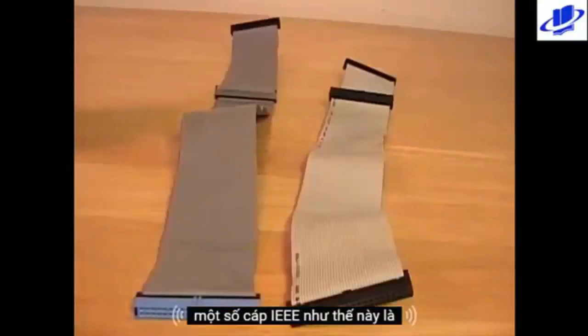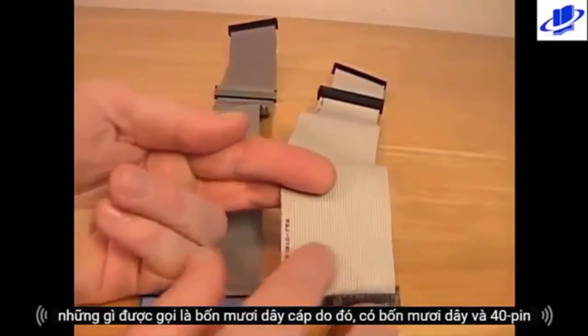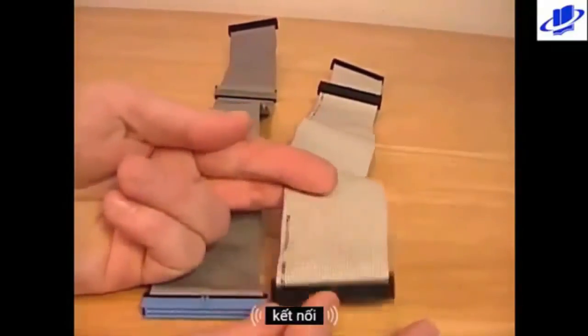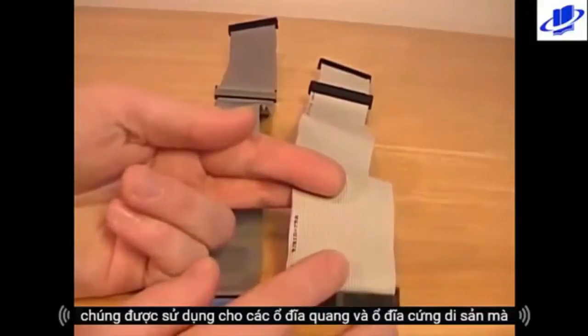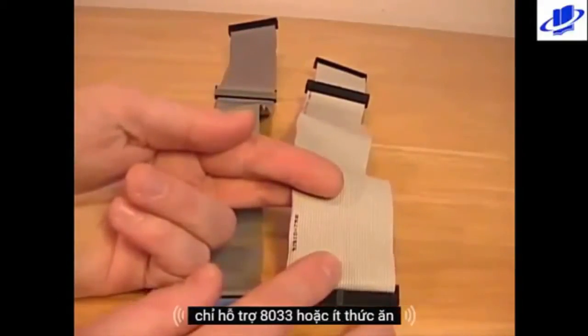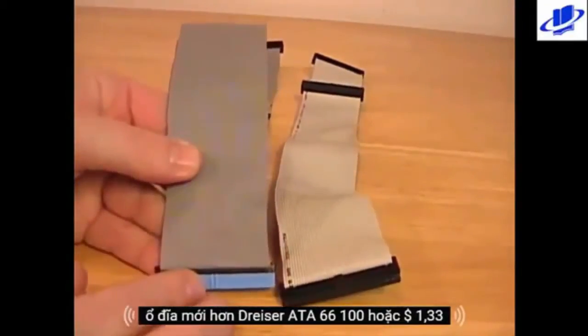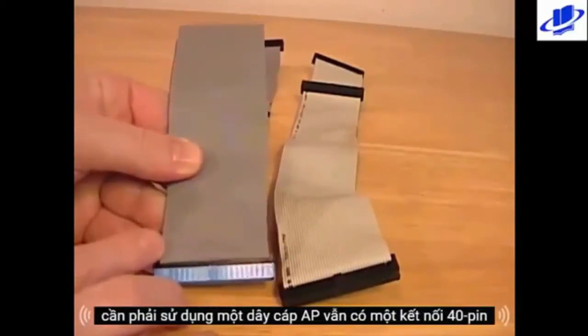Some IDE cables like this one are what are called 40-wire cables. So there's 40 wires and a 40-pin connector. These are used for optical drives and legacy hard drives that only support ATA33 or lower speeds. Newer drives that are ATA 66, 100, or 133 need to use an 80-wire cable.